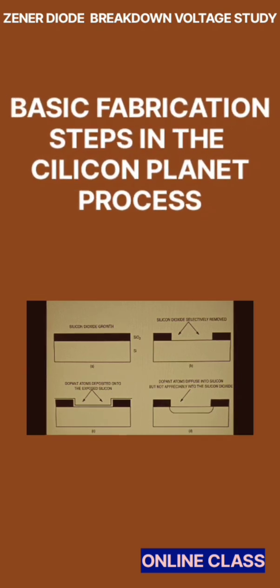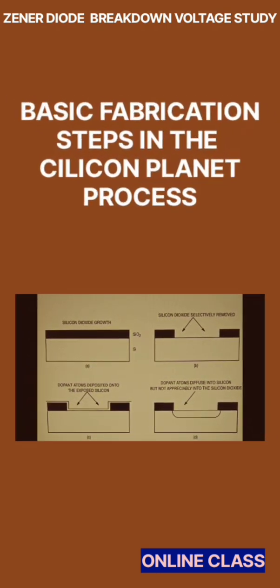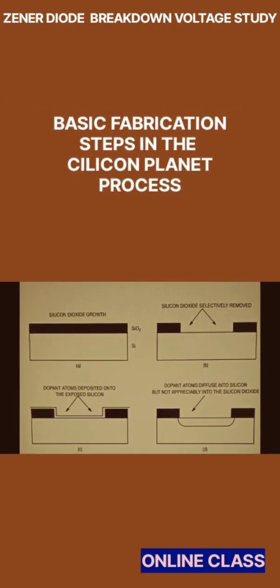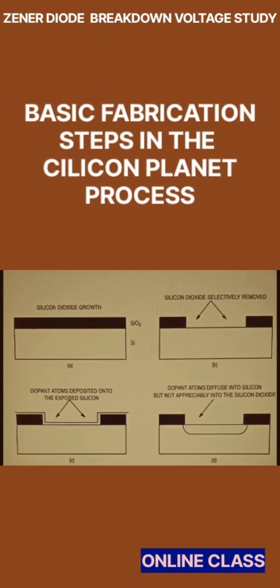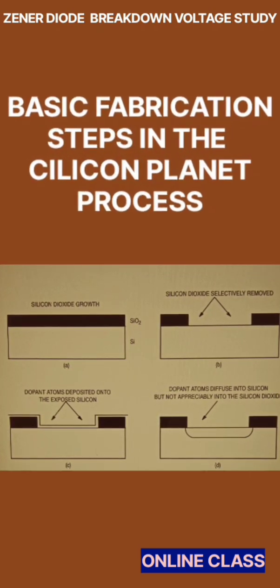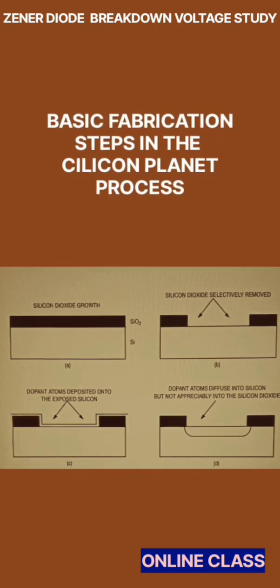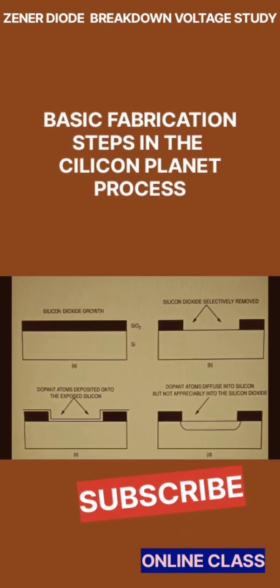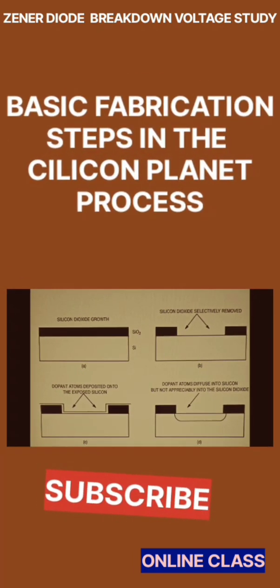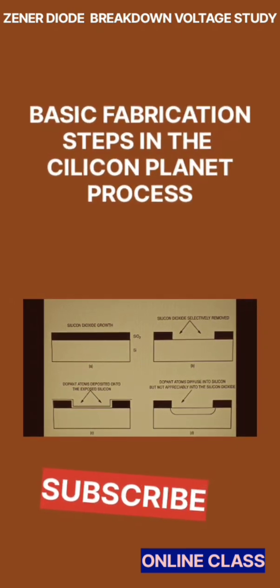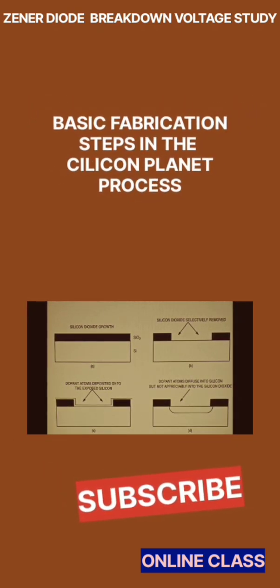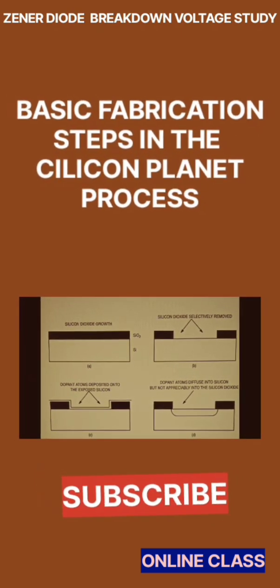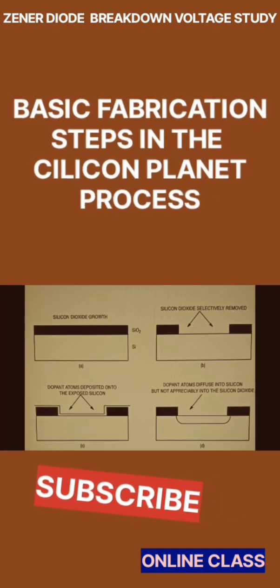After the fabrication process is finished, the wafers undergo electrical probing, inspection, and packaging for shipment to assembly operations. All zener diode products from ON Semiconductor are cut using 100% saw-through techniques that have been rigorously developed to ensure high-quality silicon dies. This is the brief study of the voltage breakdown mechanism of the zener diode control region.